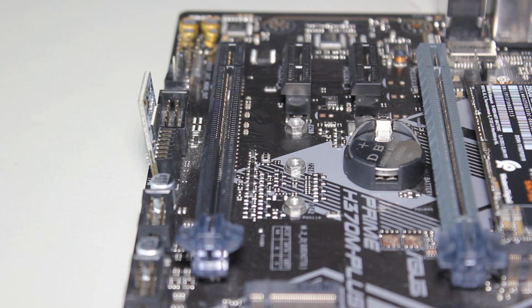Consider how difficult it can be to get these standoffs in. If I were building a new computer, I would put the standoffs in before I installed the motherboard in the case. It is just easier to do it then, rather than trying to put them in when you have expansion cards, cables, and limited room to work with.